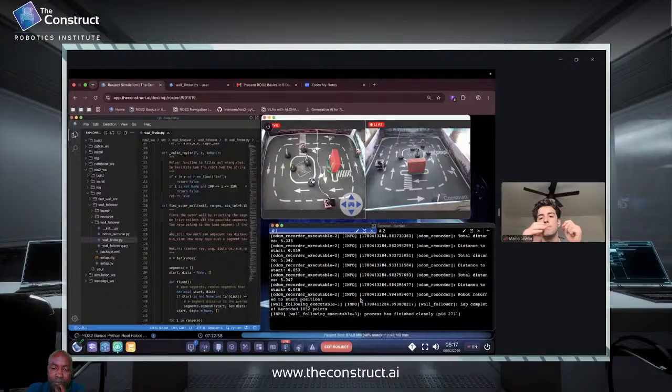So what I did instead is I used the odometry in order to rotate, where once I define the outer wall, I know which ray it is, and I calculate the yaw between the starting front ray and the wall, the outer wall ray. I calculate that yaw and I make sure that the robot turns to that yaw.